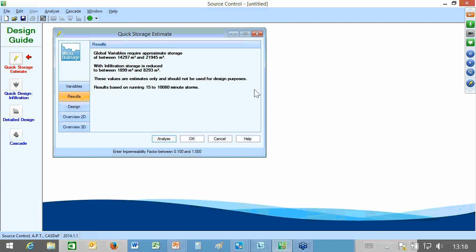The key thing here is that you can see that by just attenuating, we need, in this case, something like 17,000 cubic meters of storage beneath the ground. And when you know how much it costs per cubic meter to store under the ground, you can apply that to these numbers to see the costs of the flood mitigation measures if you attenuate.